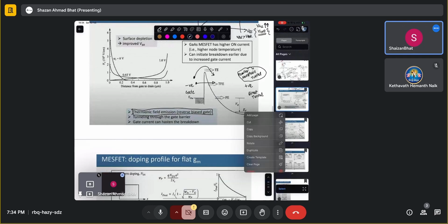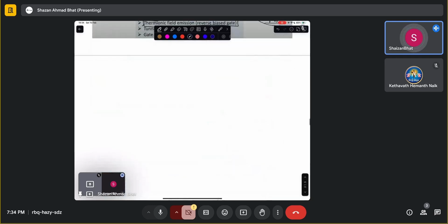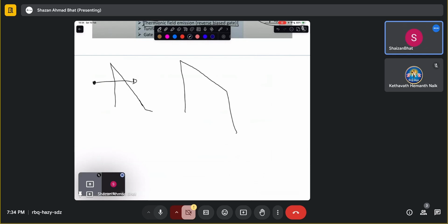Let me show you on this page, with different scenarios. If you have a triangular barrier just like this, then the electron can tunnel through it. But say this is another energy band, like an oxide, maybe silicon dioxide, the conduction band of silicon dioxide.